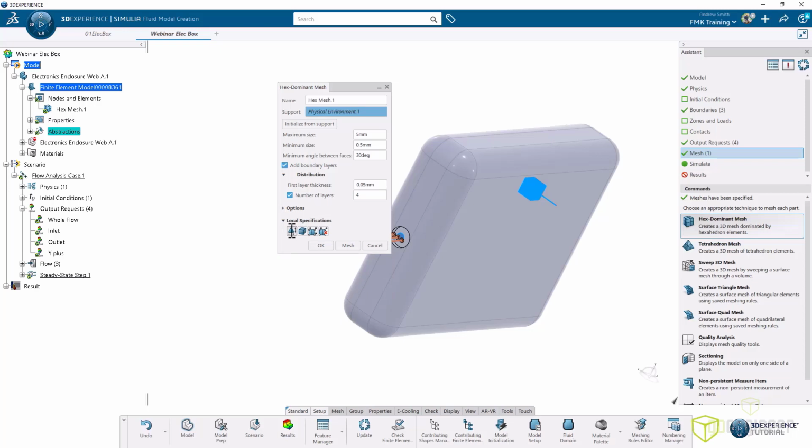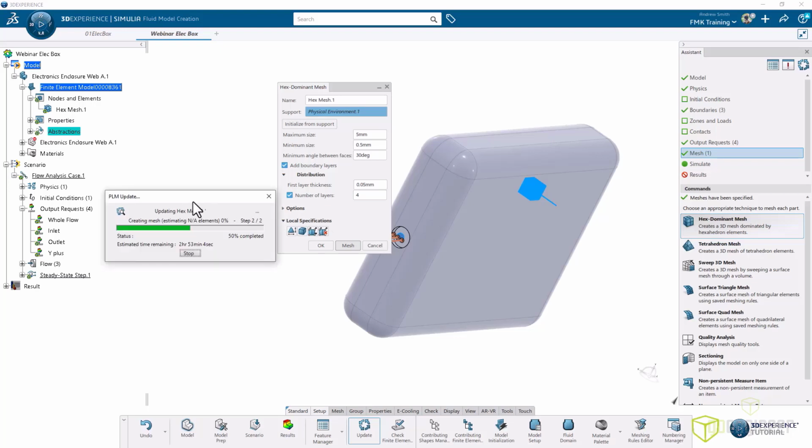So I can either choose to enhance and refine the mesh on certain faces or features, or I can make a Cartesian box that has mesh refinement in it. I don't need to do any of that now, and I can hit OK, and that'll close this window, and it'll save those settings so that when I go to simulate, it'll make the mesh. But I want to double check and make sure that visually this sort of looks like what I expect it to look like. So I'm going to hit mesh, and that'll start the mesh generation process, which takes just a minute.